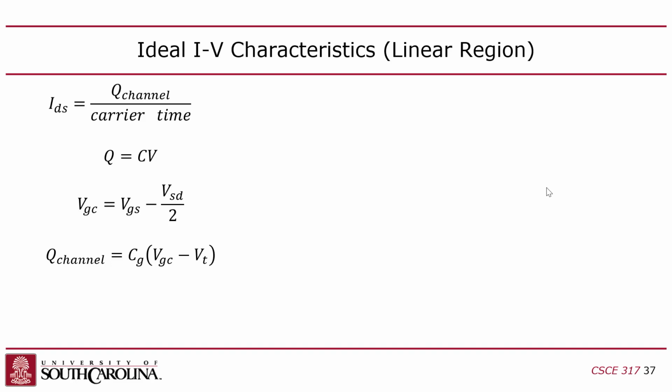The threshold voltage is a property of the semiconductor. Like I mentioned, it's usually around 700 millivolts. That's what's required to get the inversion region, and you start conducting, basically, right? So for the capacitor voltage, you have to subtract the threshold voltage. And so the charge of the channel could be calculated like that.